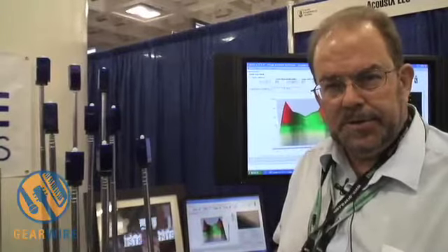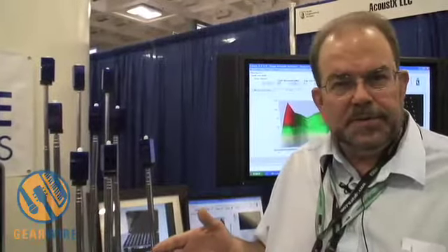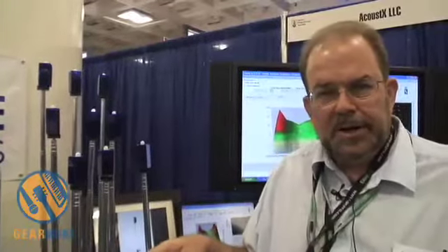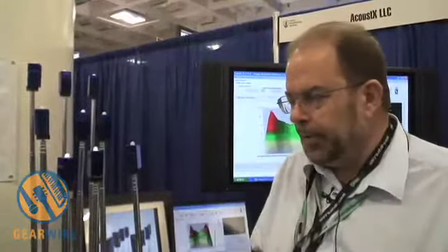The number of sensors is based on the frequency of interest. Most room modes occur below 200 hertz. 200 hertz has a 5-foot-long wavelength approximately. And if you get sensors at about 18 inches separation, you can actually see both the high points and the low points of an individual wave.